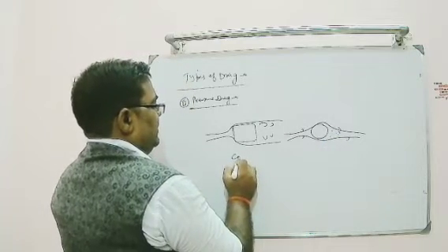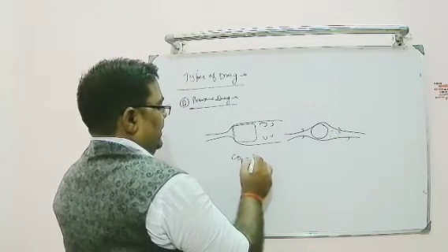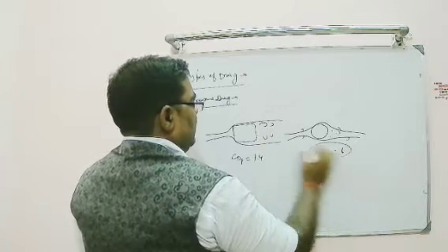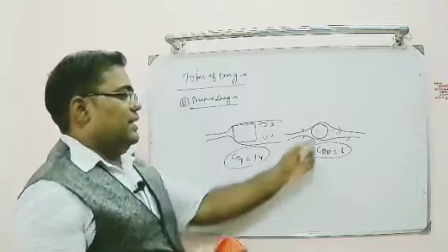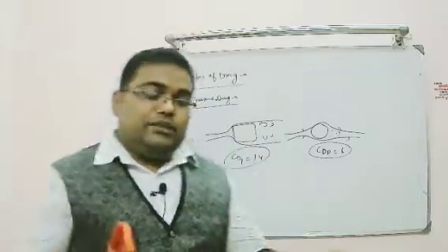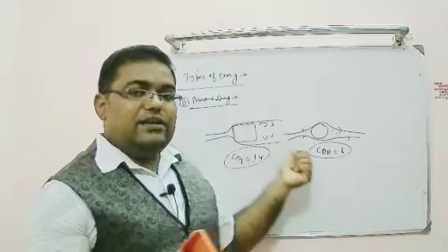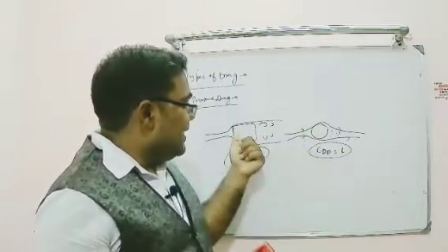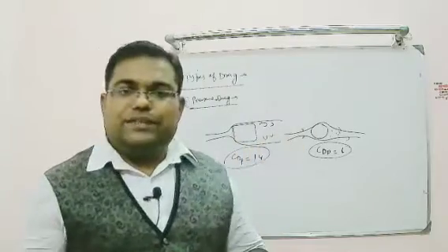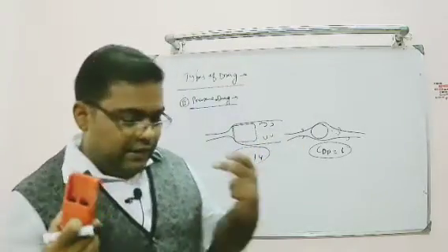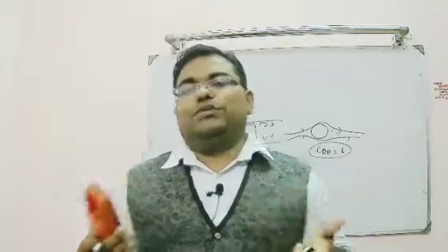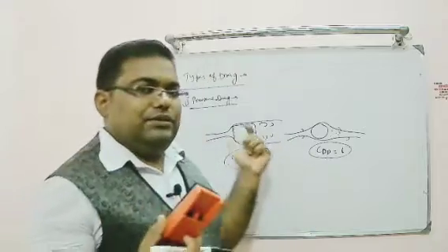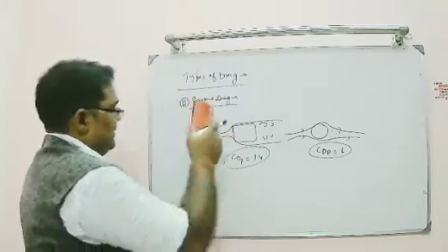So in this case, if we say the coefficient of pressure drag is 1.4, here CDP will be only 1. So look at the coefficient of pressure drag. In the case of a circular cylinder, just 1. So compared to a rectangular or square shape, pressure drag will be less in the case of a circular cylinder because it is slightly more streamlined. There are no sharp corners present, so we have to avoid sharp corners so that the flow adjusts very smoothly over the surface. If there are more flow obstructions, the pressure drag will be higher. This is the second case.